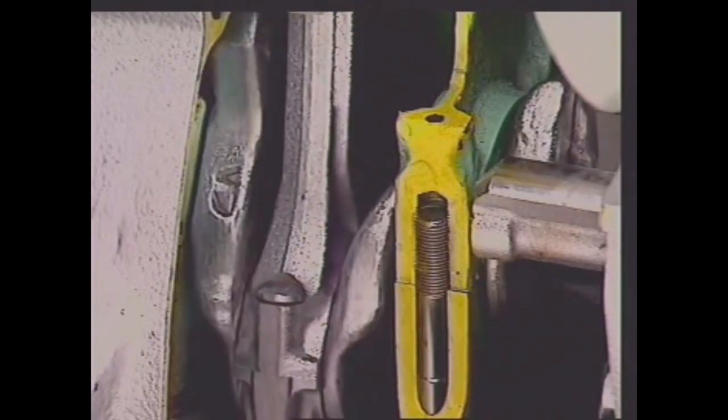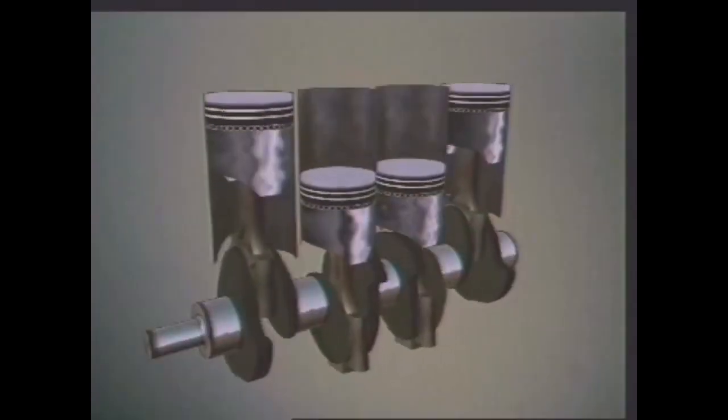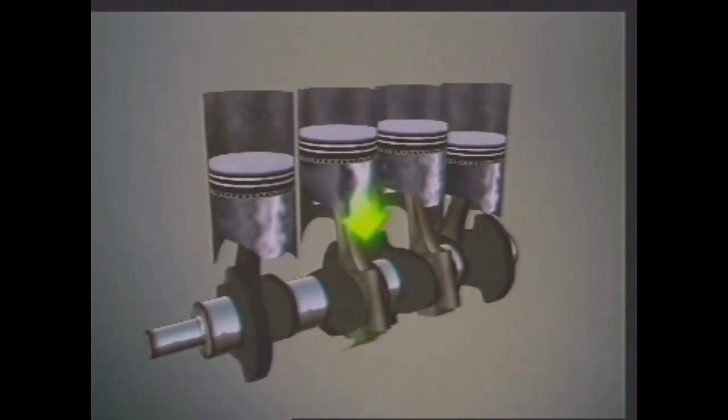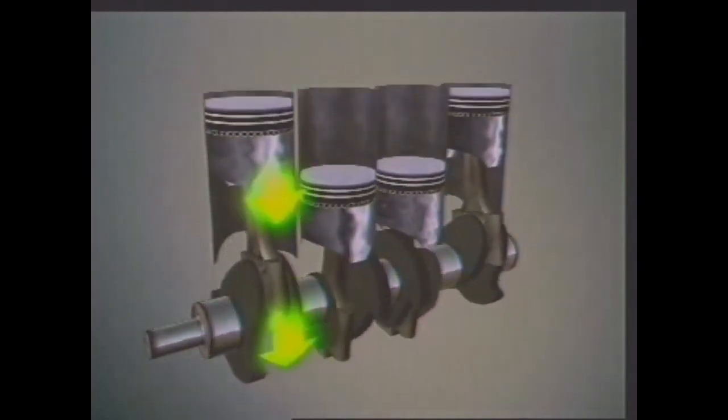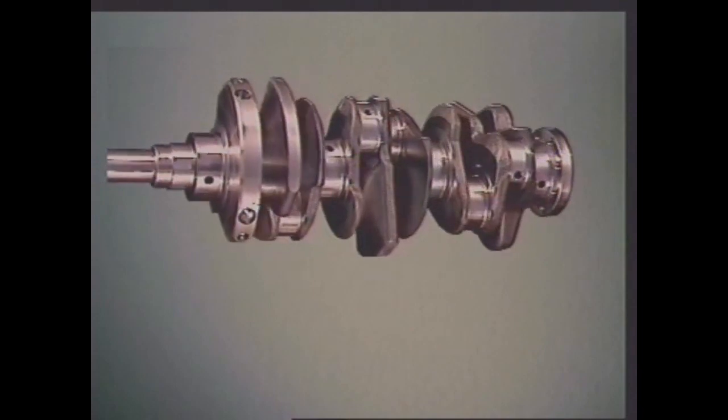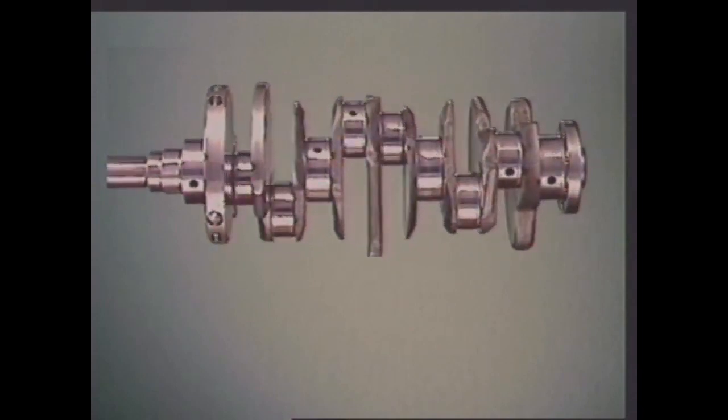Crankshaft counterweights help keep the rotating components in balance. They help keep the crankshaft turning as smoothly as possible. The crankshaft turns because of the forces transmitted through the connecting rods. At the same time, it must be held in place. That's done by bearings. They reduce friction and allow free movement. The crankshaft is held in place in the engine block by main bearings at points called journals.